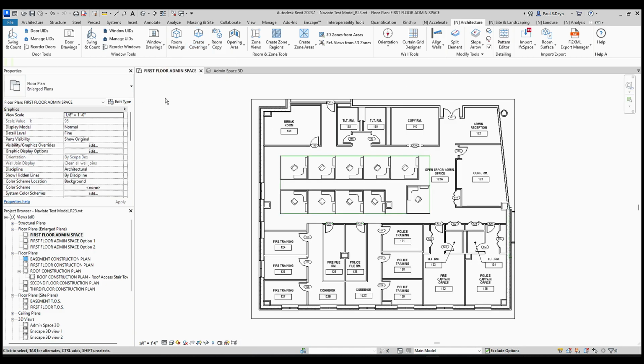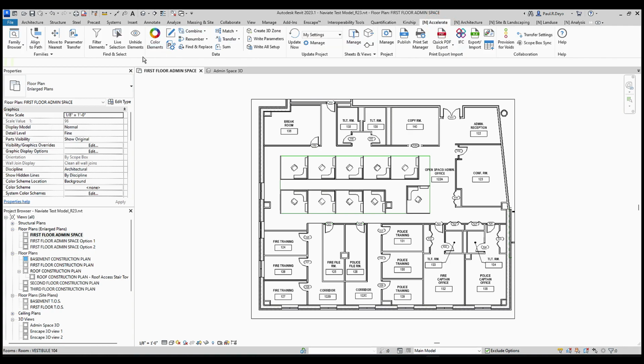The next thing I'm going to do, like I said, these spaces are spaces that, yes, I do need floor objects within, but I didn't necessarily want them to be those carpet objects. So I'm going to go ahead and just run through the process again and show you how quickly we can remove any unwanted finishes and recreate them really quickly with the Create Coverings feature again. So again, using the Naviate Accelerate Quick Filters to select the rooms I want to address.